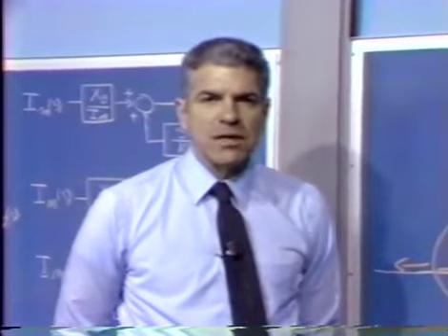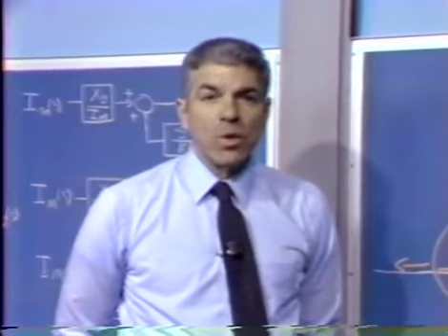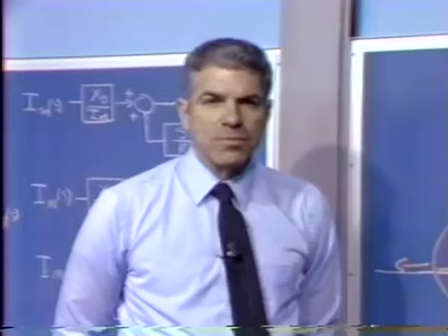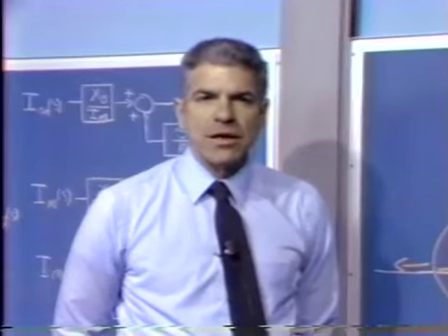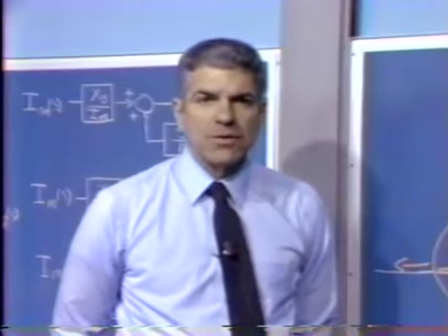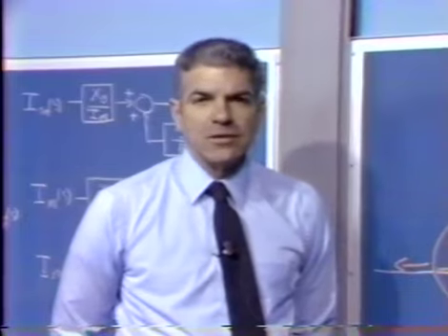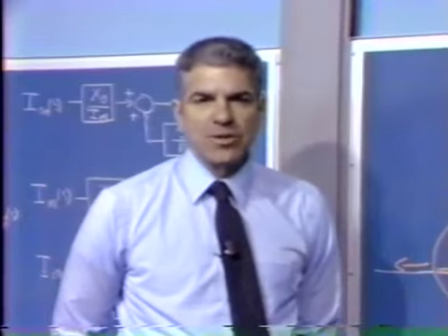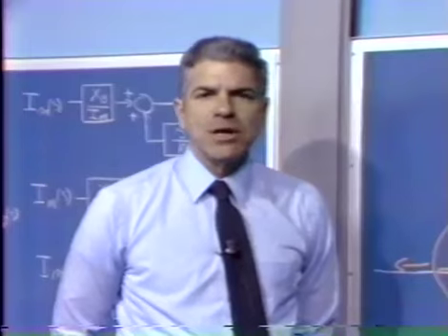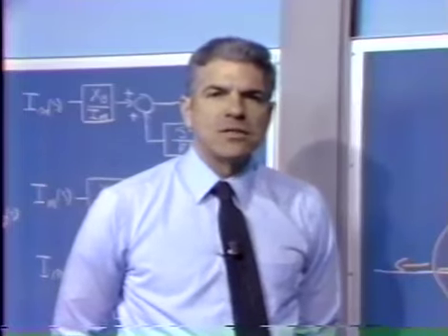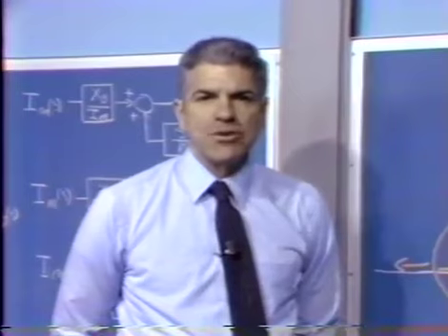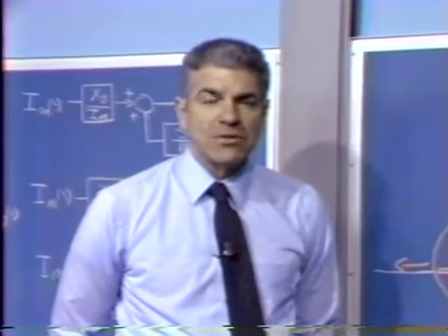If one goes into details on the sensor that's used, the way the resistance of the sensor varies with ball position and so forth, there's really a nonlinearity associated with that transfer relationship, the one that links ball position to the eventually generated electrical signal. But again, if we did this analysis in detail, we'd linearize that relationship for sufficiently small perturbations from the operating point.